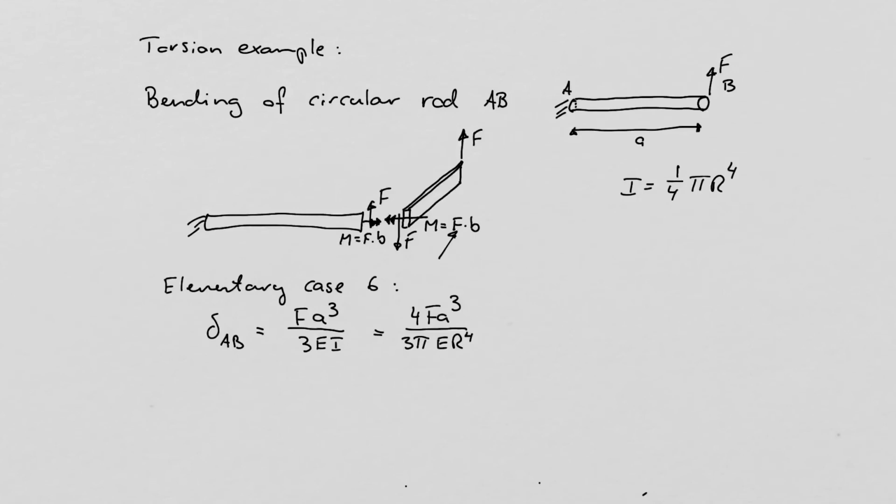So it's a bending moment on the handle BC, but it's actually a torsional moment on the rod AB. And that's because these two parts of the structure, AB and BC, are sitting perpendicular to each other. So what's a bending moment in one of the beams can become a torsional moment on the other beam. And that's most easily seen when we use the double arrow technique to draw the moments, right?